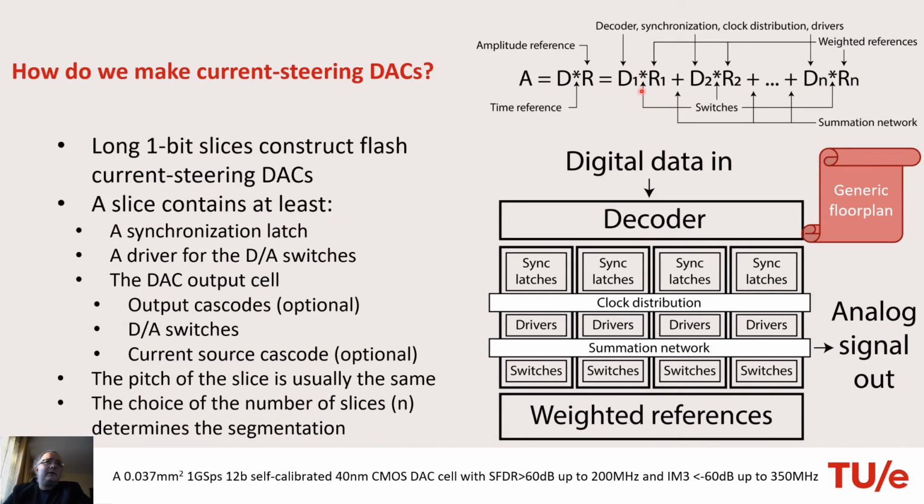The timing reference will be applied via the switches. So this here will be the decoder, the synchronization, clock distribution drivers. This multiplication will be the switches, and the sum of all these terms is the summation network. This approach is the main approach used today to physically realize digital to analog converters, the current steering digital to analog converter.